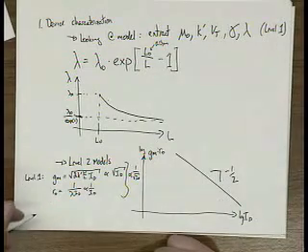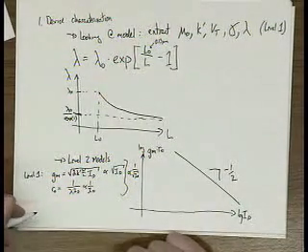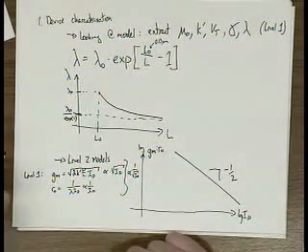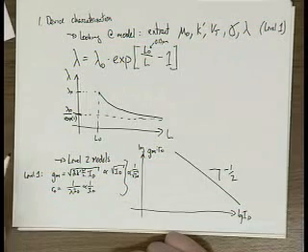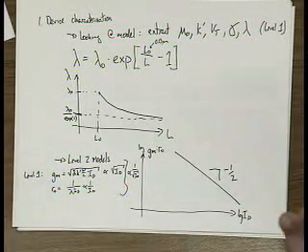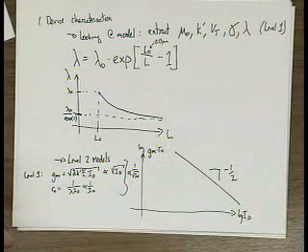So that means hypothetically, if you were to decrease the drain current lower and lower, your gain would be going higher and higher ad infinitum. So out of one device, you could get a gain, hypothetically, of 1 trillion, 1 billion, whatever you wanted, and you'd be doing it at almost no power.